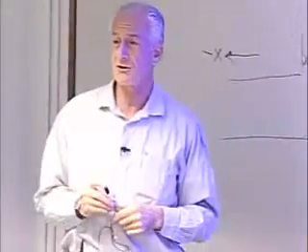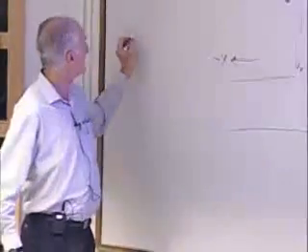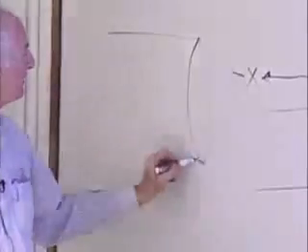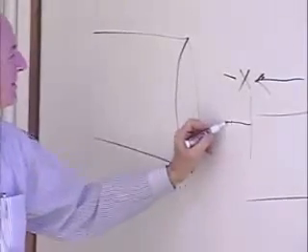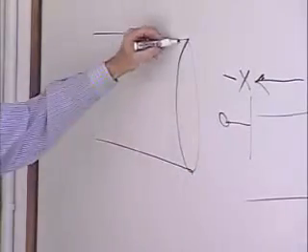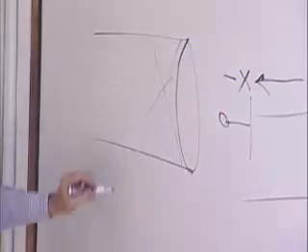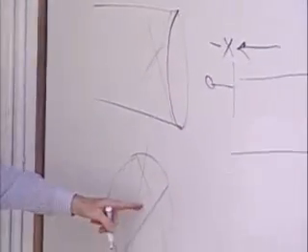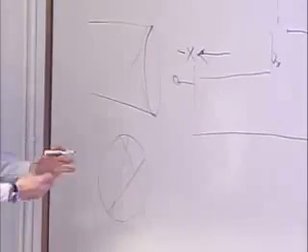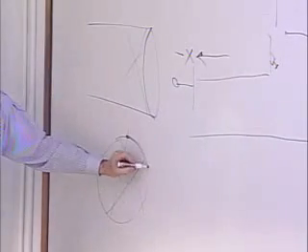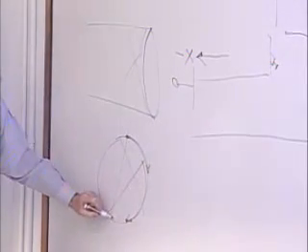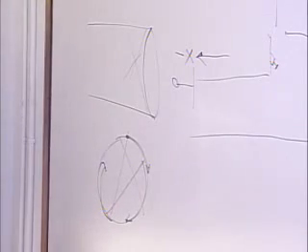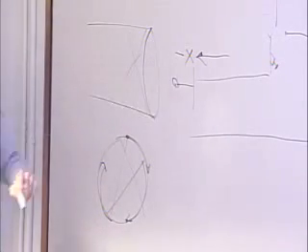They have a similar situation for the manipulator arm. On the end of the end effector, when you're coming into a grapple fixture, there are actually 3 wires inside the end effector, and those are moved around so that they tighten up over the little knob.